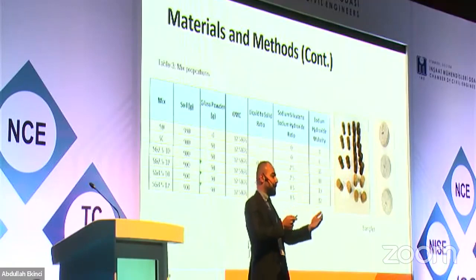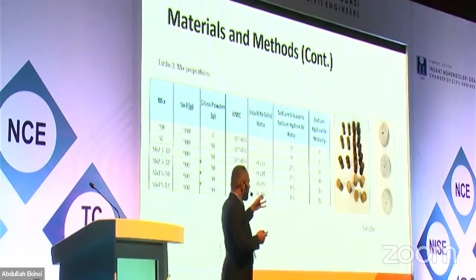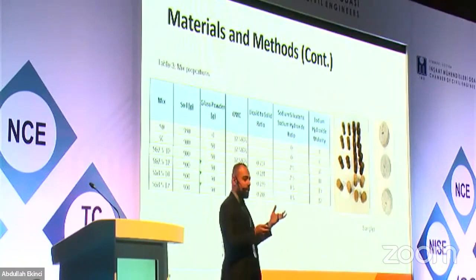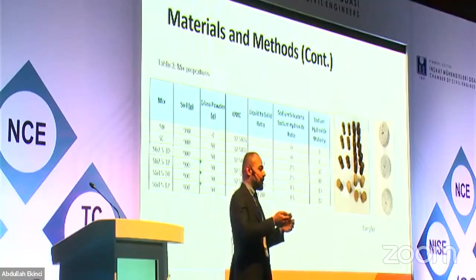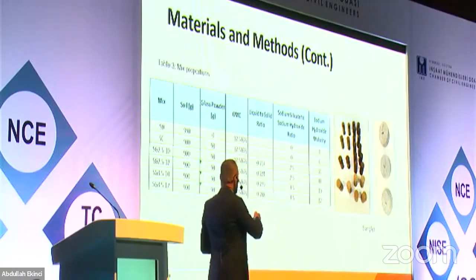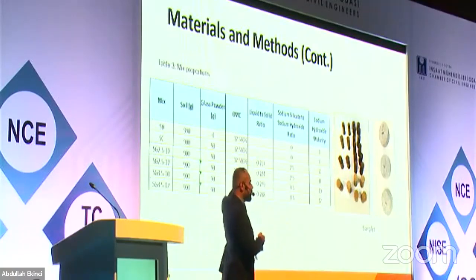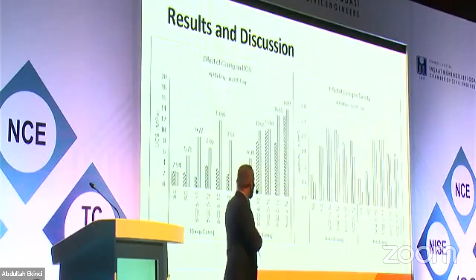As we expected, the optimal moisture content can change when you have geopolymerization. The density changes, the porosity changes, or the material that we add changes the structure of the soil that we have. But we kept the optimal moisture content based on the soil that we have.